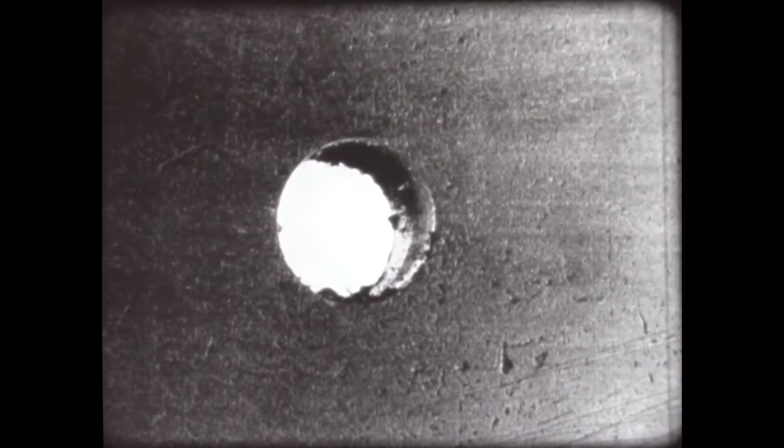The edges of a hole should be smooth. Any burrs, if they are present, cause undue wear. The hole should be clean and free of foreign particles. If not, the lapped surfaces of the gauge may become scratched and worn.